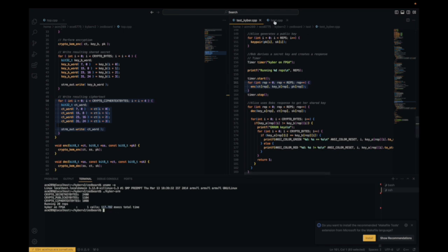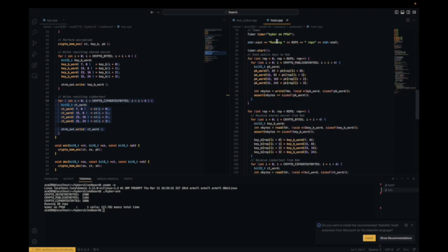Our FPGA implementation does the exact same thing, except now the design is in hardware, so encryption is turned into reading and writing all of the hardware input and output streams. We first send all of the inputs, then read all the outputs to amortize communication latency. Here we can see that the latency in the execution time is drastically lowered. Now we're only at around 83 milliseconds.